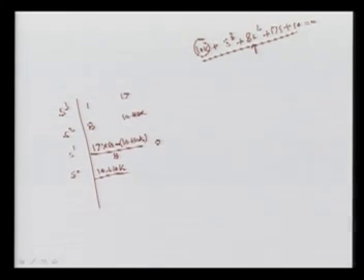So what we have to see for the Routh criteria is that the first column should be positive, and let us see when the sign is going to change. Here the first criterion is that 10 plus 10k should be greater than 0. It must be positive. So here we are getting k should be greater than minus 1, and that is always true. For another condition, from this one it should also be positive, so I can write 17, divided by 8, minus 10 plus 10k divided by 8, must be greater than 0.